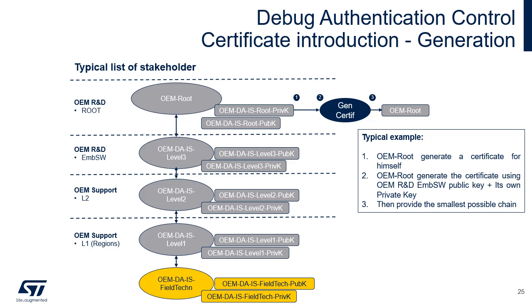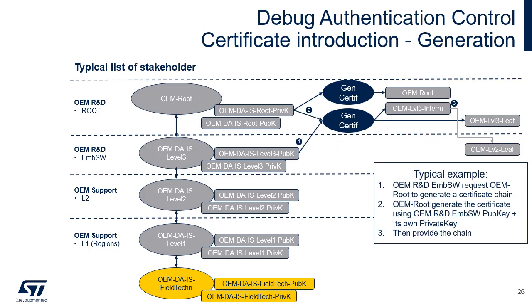This is basically a structure. This structure that includes the public key is hashed and signed by using the private key. Once generated, the certificate is stored in the OB key related to the minimum HDPL accessible from the OEM. In the OEM company, 2 levels are distinguished: development of secure applications and development of general-purpose embedded software. Isolation is needed between the 2 teams. This is why a separate certificate is generated for the second team.